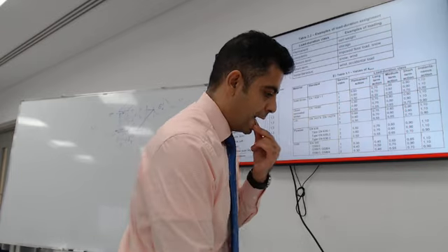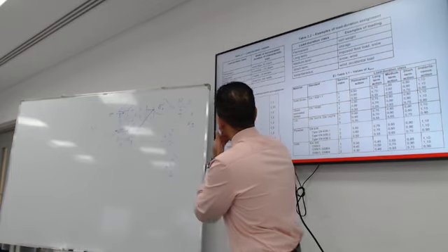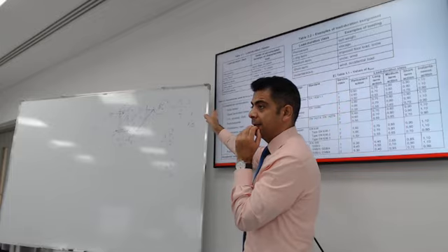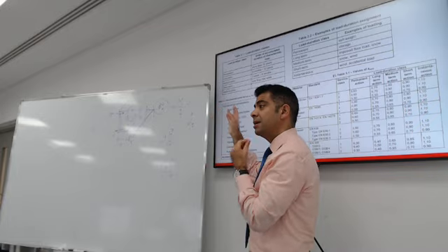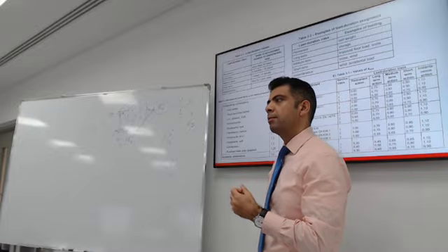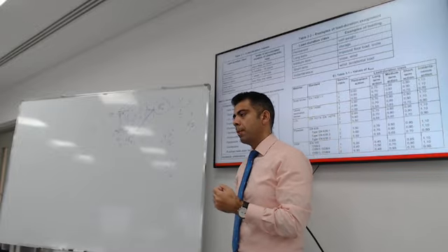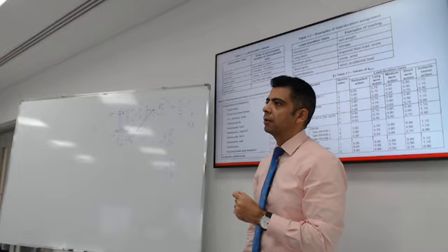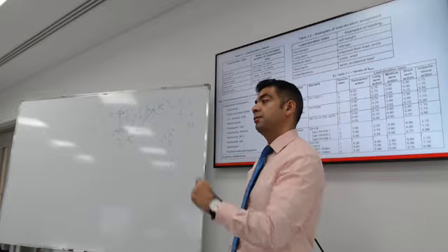All right, there is one more table. This is the material factor of safety, gamma M. In steel, you guys are used to taking it as 1. That's a Eurocode thing, by the way. Different standards might use it differently. Might actually put some factor of safety for steel.